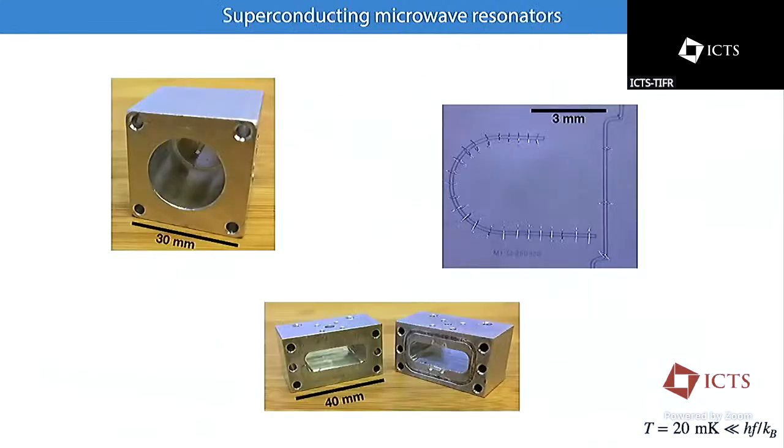And we can construct superconducting devices like this, because something we have for free at these temperatures is that many materials like aluminum are superconducting. So we can construct superconducting geometrical structures, either on chip, like this coplanar waveguide resonator, or in 3 dimensions. These structures will resonate at a few gigahertz. You see this rectangular cavity here, it resonates at about 8 gigahertz, for instance, for these dimensions.